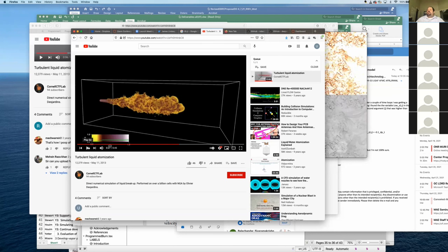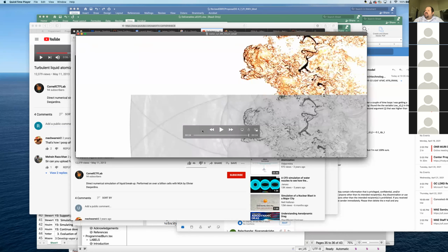And these VOF methods, they're used for all kinds of things. They are used to study the wakes that form around ships, all sorts of gas-liquid flows. Okay, and then I also discussed the so-called THINC method, which is halfway between a diffuse interface method, where you don't use any special treatment of the interface, you just solve them using your normal compressible flow algorithms, and THINC is sort of like a VOF method, but not quite as complicated.